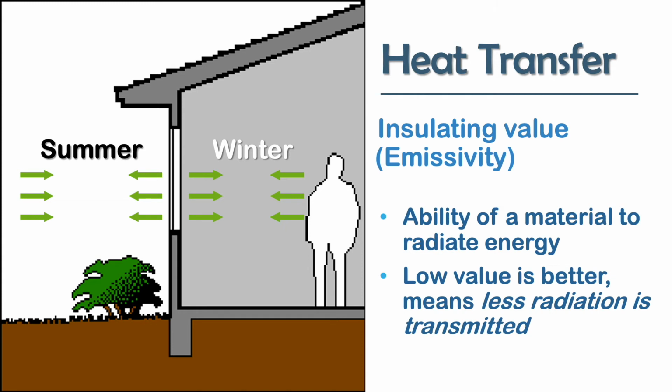Objects outside of the building, such as black parking lots and neighboring buildings, absorb heat from the sun and re-radiate it in the form of long-wave radiation. Again, glass with an emissivity of 0.04 will keep 96% of this long-wave radiation out of the building and thus reduce the need for supplemental cooling.